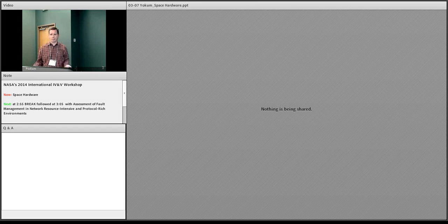Again, 1553 and SpaceWire tend to be the two de facto communication standards for most of the space missions, at least that I've seen to date. So some of the things that we could do for the facility with the 750s, we can execute the full VxWorks and RTEMS operating systems. We have done both of those, and we've done VxWorks 5, VxWorks 6.4, and ran RTEMS. So any of the interactions we want to see with the operating systems and the hardware, we can do that.